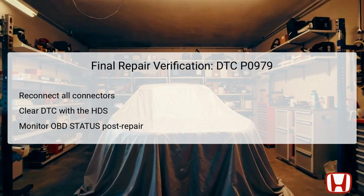After this, conduct a test drive in third gear for a duration of at least 1 second to check the system under operational conditions. Finally, monitor the OBD status through the HDS for DTC P0979. If it displays as passed, it confirms the repair process is complete, and if any other DTCs are present, further investigation into those codes will be necessary to ensure comprehensive vehicle functionality.